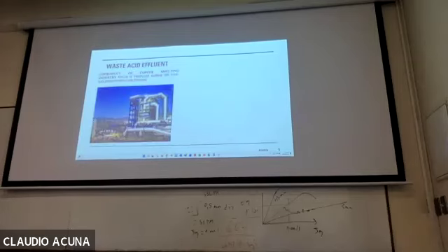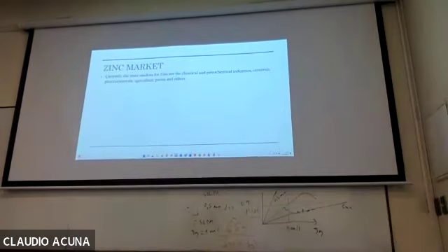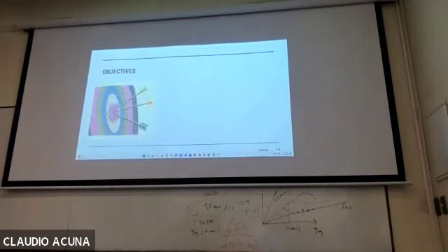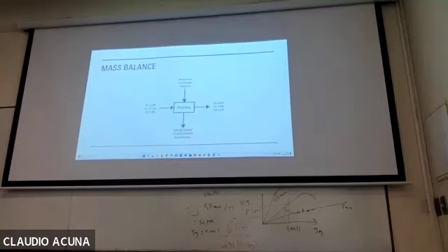You have the mass balance. Okay, come back to the last one, the mass balance. A mass balance with the compositions only is not good enough. You need to have the total amount, to see what we're talking about, 1,000. Actually, I was calculating, listen up: 375 cubic meters per hour. So you're going to need a huge reactor.